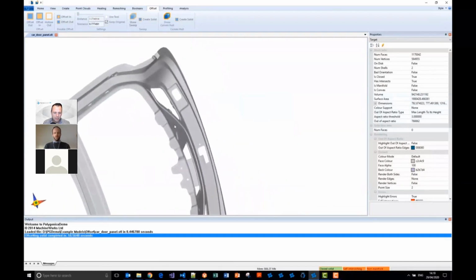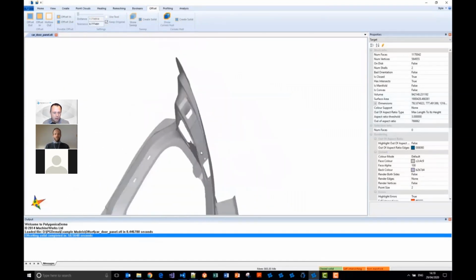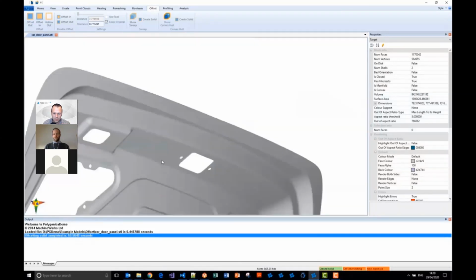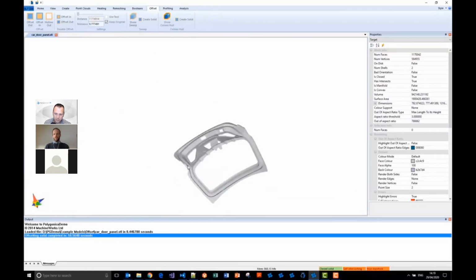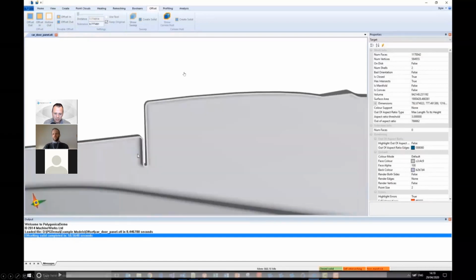But now this part is solid. We thickened it by 1 millimeter. It's something that can be printed now. You notice the number of triangles has increased, and it was done with a spherical offset. So if we go back and zoom in, you can see that it does have a thickness, and in that one feature, that kind of fold over, let's take a look at that as well. So here now we've altered our mesh. You also saw at the very beginning, the toolkit reported that this is an open surface.